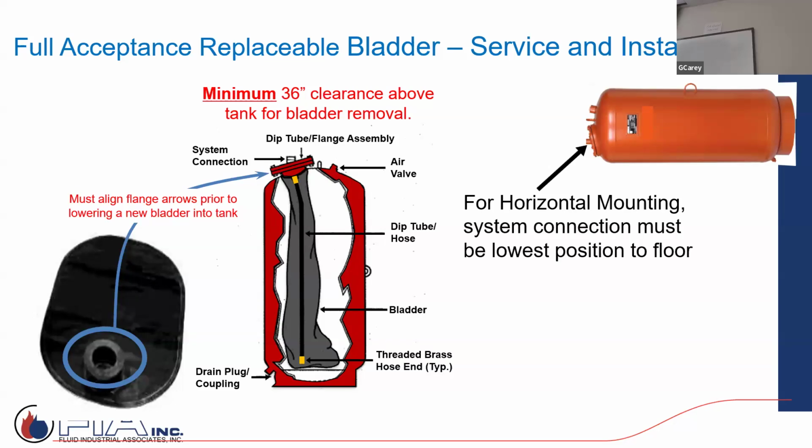He said, hey, you either got to change that diaphragm tank from a non-ASME to ASME, or you got to get new. So we reached out to the boiler manufacturer and said, hey, can you send us a new official label from you that said 30 PSI? You'll see it commercially, they pay attention all the time. Manual resets on boilers have to have that manual reset button. You can't just have an auto reset low water cutoff. You have to have that manual reset. So they go around the mechanical room and they look for things.